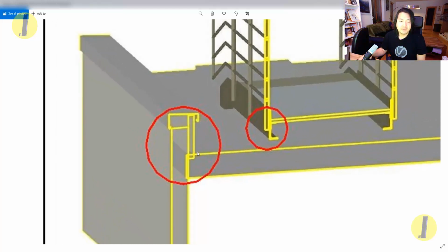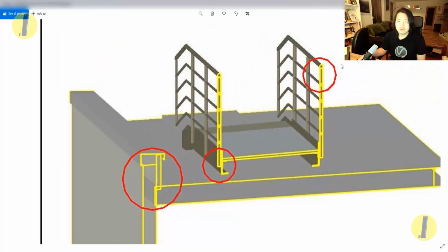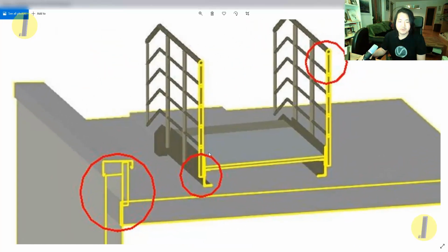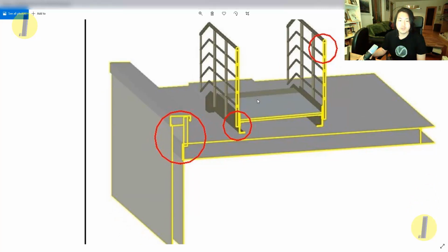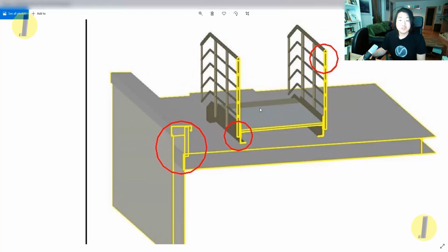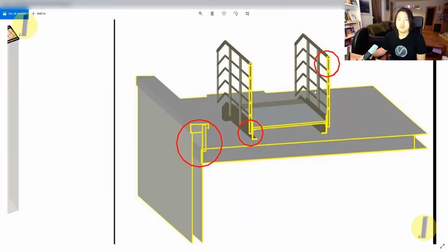So in this case, this sort of architectural detail and the collisions between architectural finishes can be acceptable, because in most cases you are solving these detail errors with a 2D drafting view, for sensitive stair details or railing and handrail details. If there's a collision, you can make a rule. If you really want to filter all the collisions, maybe these will give you millions of collisions, so it's better to accept them from the beginning, so you can really achieve a collision-free model.